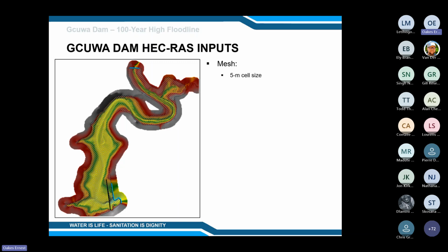But just to be slightly conservative towards risk, I decided to rather leave the mesh size at 5 meters. Also because, as my colleague Brandon alluded to earlier on, if you start to increase the detail of your time steps or even your spatial information, your simulation times tend to get quite long. And because we had to do numerous simulations just to do various testing for this particular project, and just to improve the turnaround time, we decided to rather leave the mesh cell size at 5